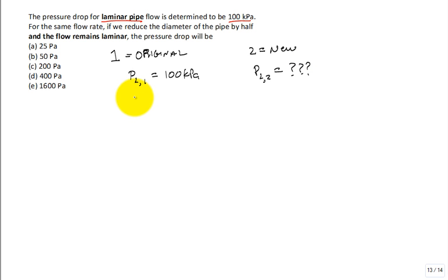The flow is laminar, but what you do is you have the diameter of the pipe given, but the new diameter of the pipe is 1/2 the original diameter. True? We have A1V1 and A2V2. So what is the volumetric flow rate? It's the same volumetric flow rate. True? So try to organize the information as you're going down.